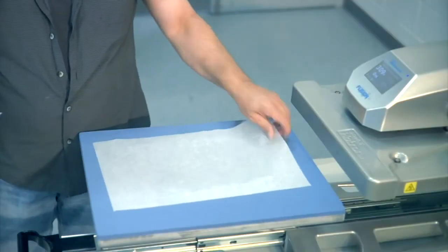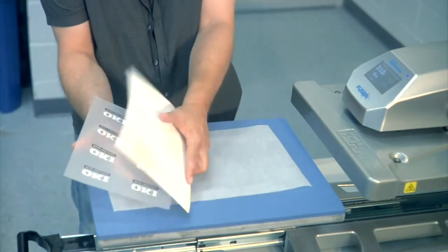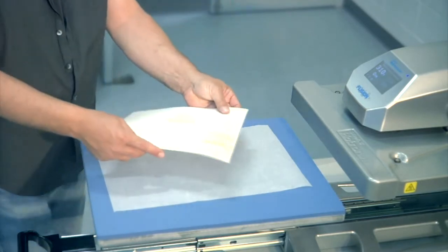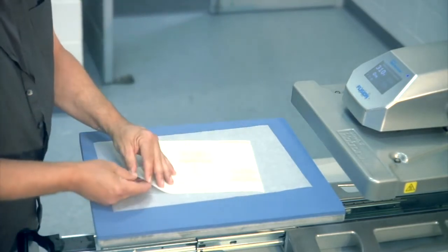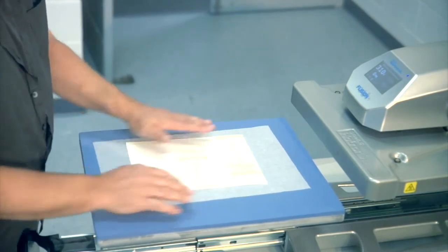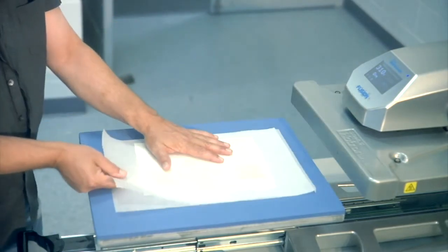Pressing the transfer. When you're pressing onto dark shirts, the printed A sheet must first be pressed onto a B sheet. Place the printed side of the A sheet face up, then lay the white side of the B sheet face down on top of it. You may want to lay down oversized sheets of plain paper or parchment. This protects the platen and foam pad of your press while also slowing down the cooling time of the transfer after pressing.